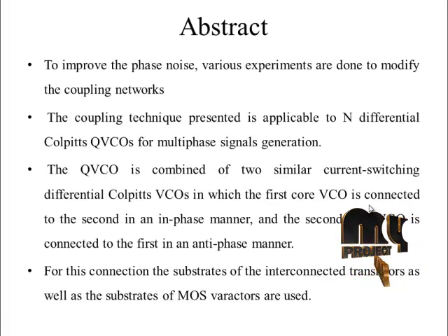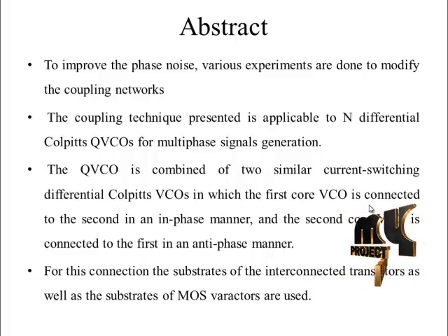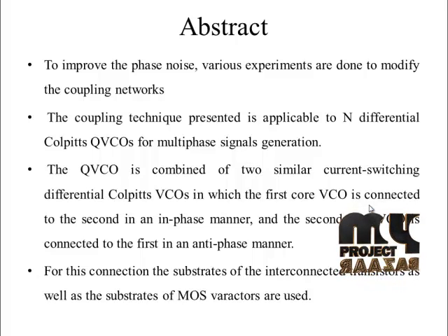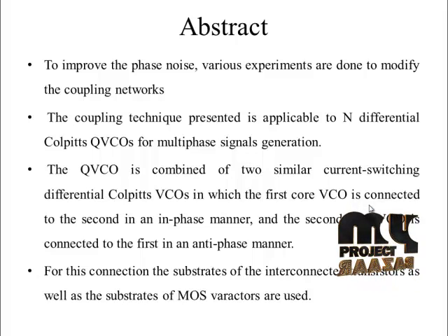A new low phase noise, low power quadrature voltage controlled oscillator, called QVCO, using differential Colpitts oscillator is presented in this process. The proposed QVCO is composed of two identical current switching differential Colpitts VCOs, in which the first core VCO is coupled to the second in an in-phase manner, and the second core VCO is coupled